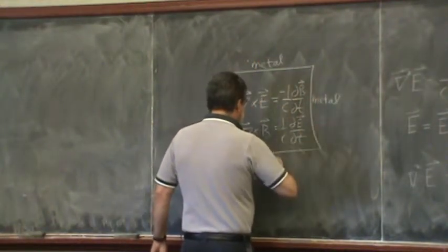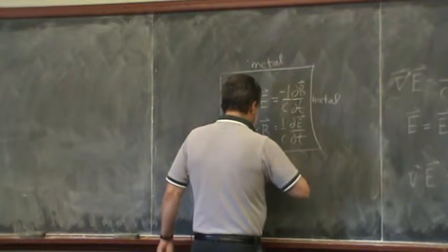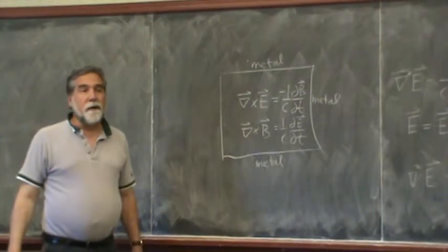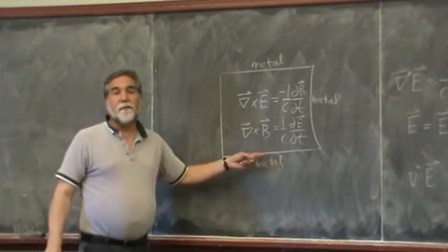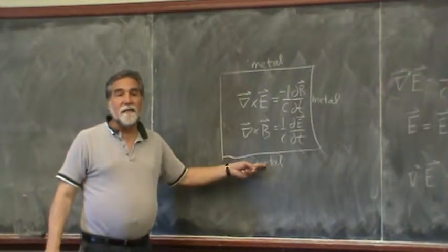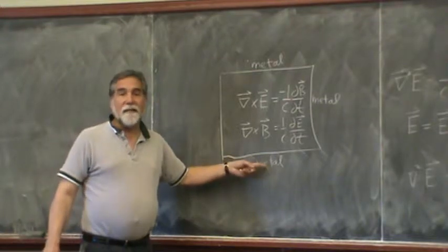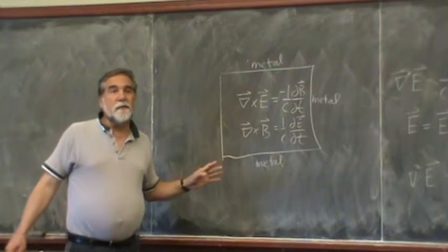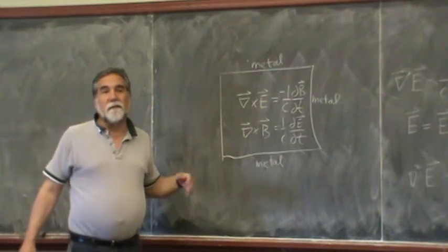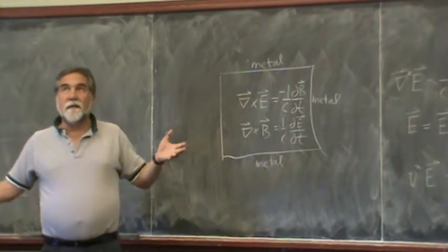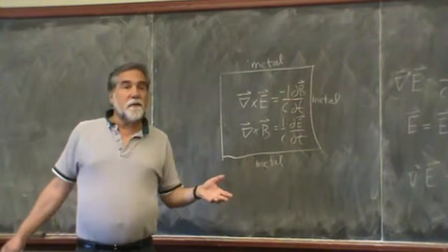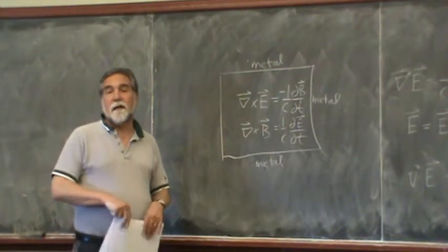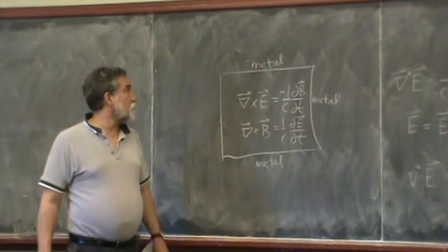And now we ignore the properties of real metal that we talked about, where the electromagnetic field actually penetrates some distance into the metal. We've got a skin depth. We say the skin depth is 0 because it's small, usually. Let's say for microwaves, we're talking microns, and the wavelength in vacuum is centimeters. So it's very small. We're going to just treat these as ideal conducting metal walls.